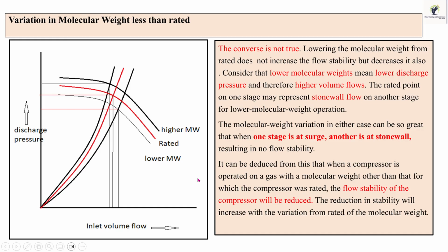So, with changing molecular weight while your compressor is running, one time it may go to surge and another time it may go to the stonewall, depending upon the change of molecular weight of the fluid you are handling. So, while running a compressor, you have to be very careful. There should not be any change in the molecular weight.